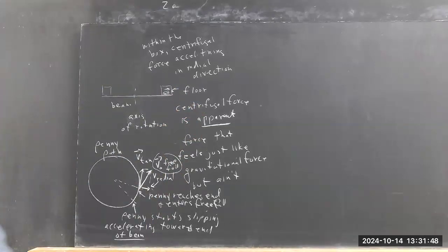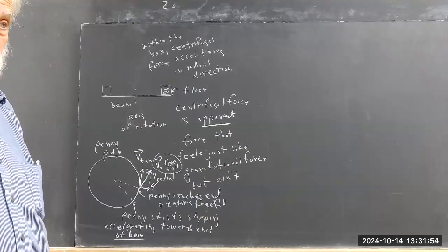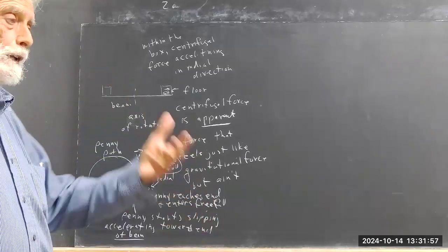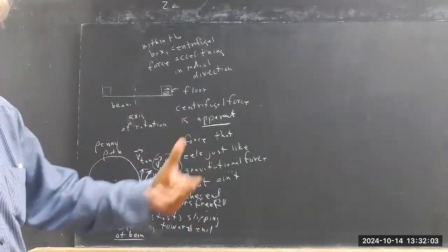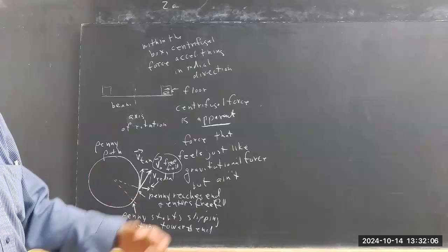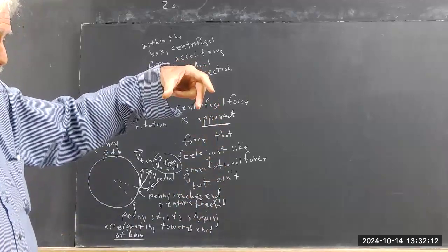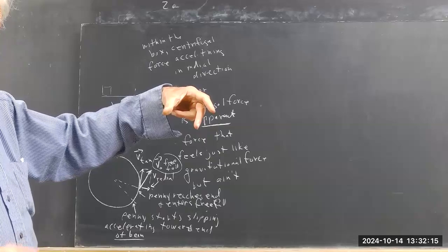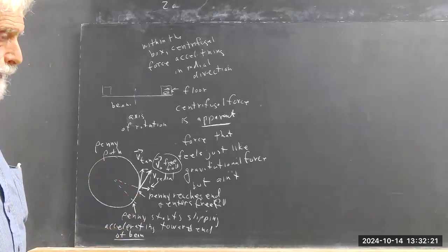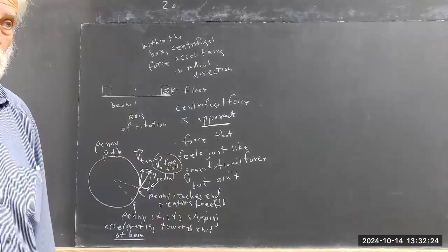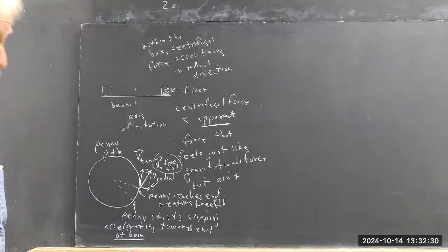Now we can measure the coefficient of friction. I think it's between 0.3 and 0.4, somewhere around there. That's static friction. Kinetic friction is probably going to be a tenth lower, ballpark. We can measure those things. We will in lab. We did it just heuristically, with a 60 centimeter meter stick. We had to raise the end up about 30 centimeters, with the magnet sitting on it. Then it started to slide around that point. That gave me an idea of what the coefficient of static friction would be. We got the tangent of that, 30 divided by the 60. That was what it really was.